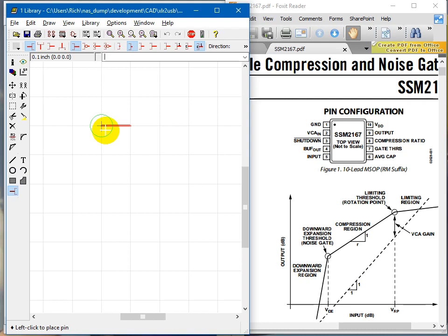Names and text labels begin with a tick, just like kind of in Excel or something like that. They don't have to end with a tick. So they just tell Eagle, this is text, it's not a coordinate or any other things like that. The command line structure is a little funky in Eagle, but you get used to it after a while. Anyway, tick for name, and the name will be called ground. Capitals, ground. I'm going to use the @ symbol, 1.